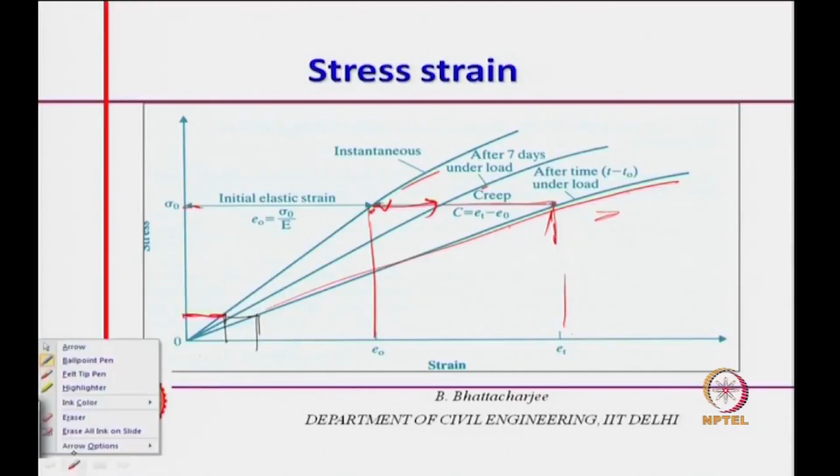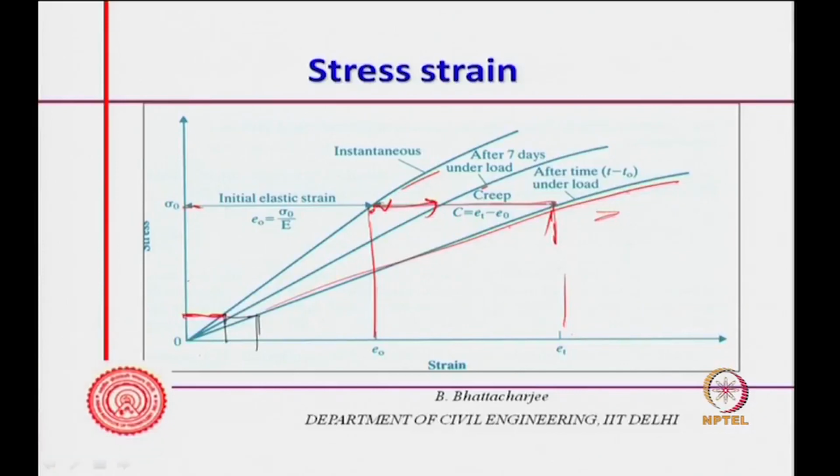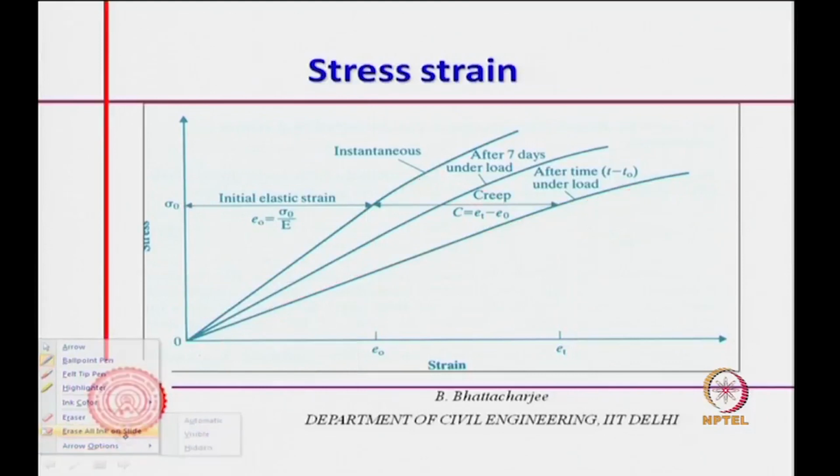If I consider this stress level, this is the instantaneous strain, and this is the creep strain. So, at any point of time, at any level of stress below the failure, below the strength level, you find there is always creep. So, that is what we define as creep, right.